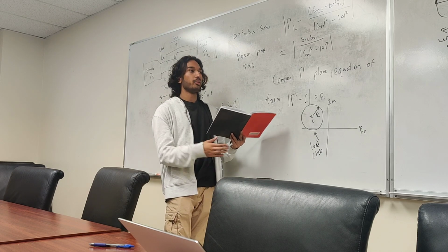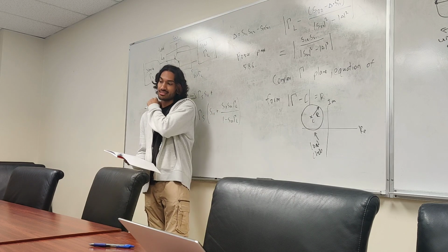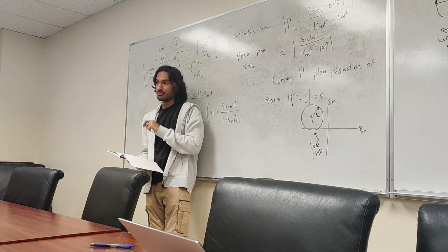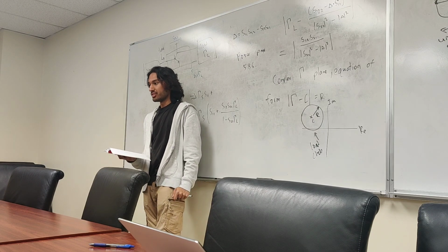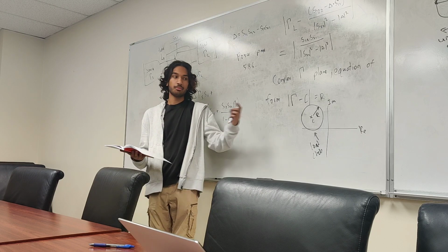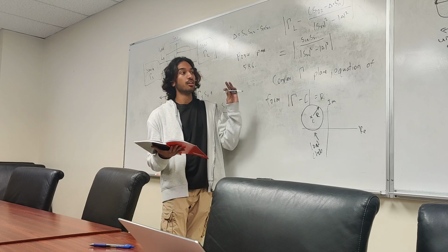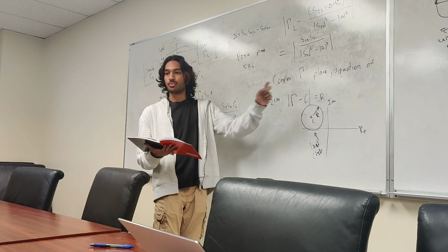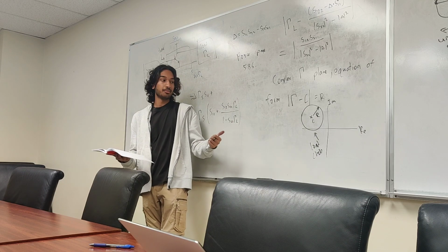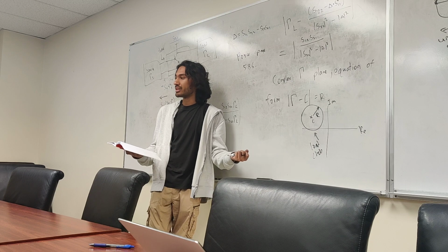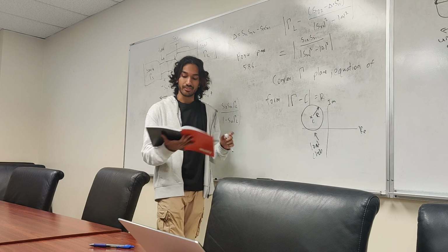But because of the way we have modeled our networks with these S parameters, with these reflections, the key takeaway is if we're not matched at 50 ohms, we can potentially have a maximum somewhere else. Meaning that if everything's 50 ohms, we'll get some gain, but it might not be the max. And if we want the max, we have to find out what that max is, where it is, what source and load networks it requires, and match to that instead, not 50 ohms. It may line up that the max gain is at 50 ohms, depending on what values you have. But generally speaking, that may not always be true. That's the important takeaway you should get from this.